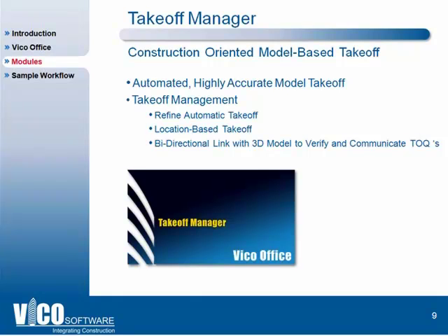The Takeoff Manager is the first module that will be available in the Vico Office platform. Takeoff Manager takes the properties and the geometry from BIM elements published from ArchiCAD, Tekla, or Revit, and automatically creates takeoff groups, and we call those groups takeoff items. When the model is activated inside Vico Office, quantities are extracted from the BIM elements, and we do that using our own geometry analysis algorithms. So all the quantities are calculated inside the Vico Office environment.